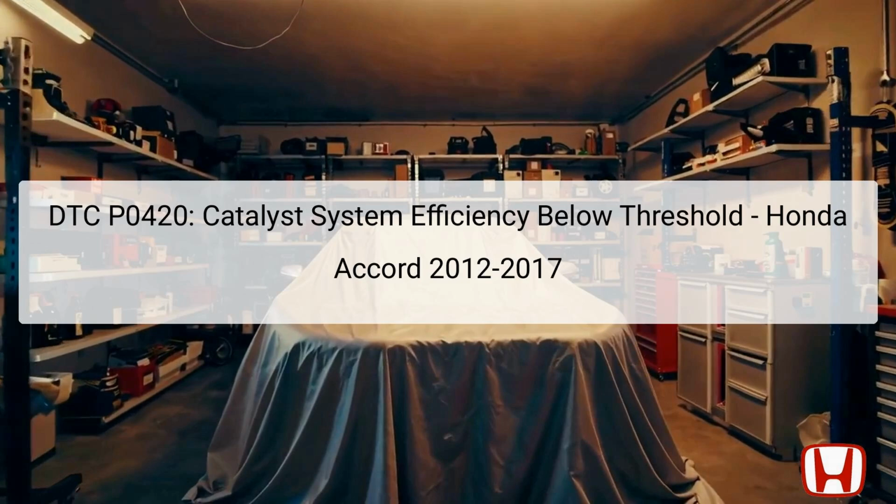The Diagnostic Trouble Code, DTC P0420, indicates an issue with the catalyst system efficiency in the Honda Accord models from 2012 to 2017. Specifically, this DTC is triggered when the performance of the warm-up three-way catalytic converter, WUTWC, is below the expected threshold. The WUTWC plays a crucial role in converting harmful gases in the exhaust, such as hydrocarbons and carbon monoxide, into less harmful emissions, including water vapor and carbon dioxide.